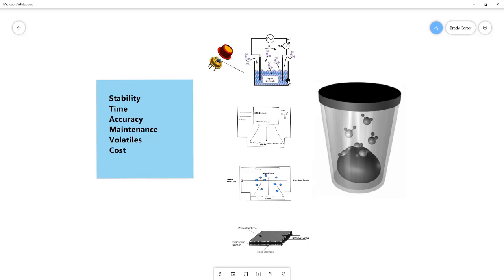The electrolytic sensor is next in sensitivity because it cannot have volatiles in the headspace. It will impact its reading, and if there are certain types of volatiles, it can have an irreversible change. The solution for this particular sensor is to use filters to keep out certain types of volatiles. But then with the chilled mirror, the problem with the dew point is that when the mirror is chilled, there will be volatiles that will co-condense on the mirror, and they will impact subsequent readings, and there's really no way to avoid that. So with this particular one, when you have volatiles present, and they're specific volatiles, but if they are present, the only choice is to not use the sensor.